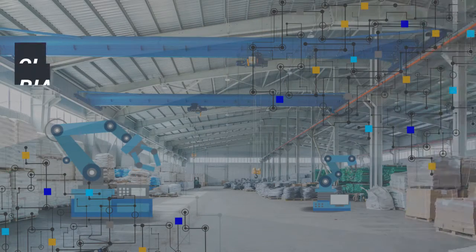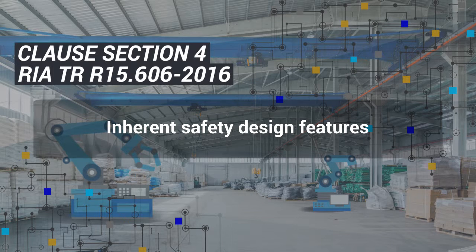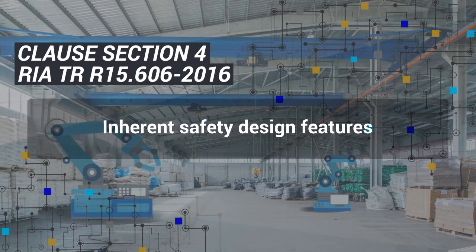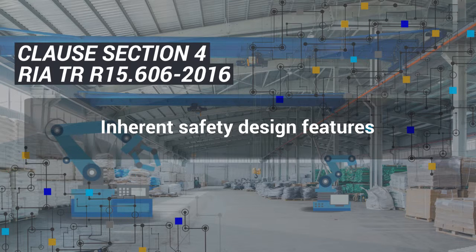There are two central concepts in the technical report, which are collaborative robot systems design, Clause Section 4, and requirements for applications, Clause Section 5. Clause Section 4 talks about inherent safety design features, which incorporate requirements for design factors, hazard identification, and risk assessment. It also addresses an approach to mitigate and reduce the effects of a hazard.